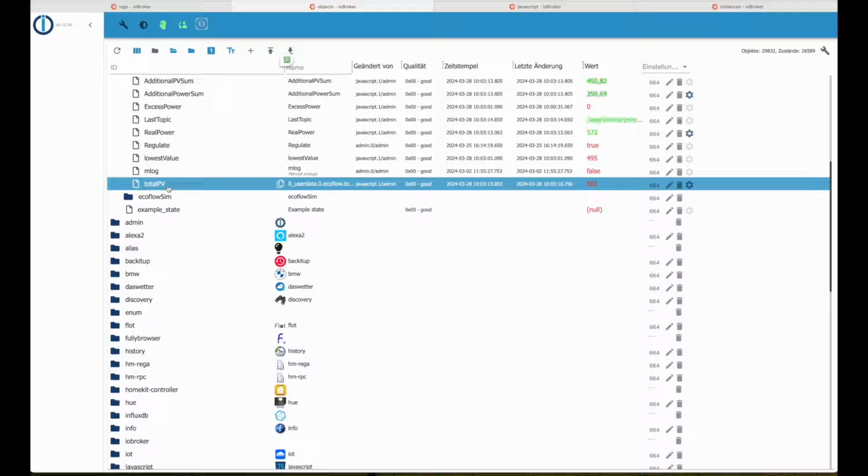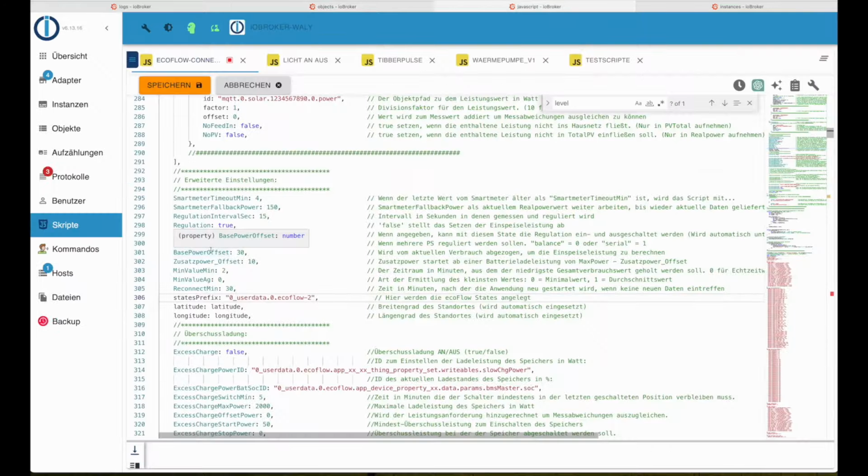If you go to your PowerStream there and look at the household power demand point in the settings, you should easily notice that the script dynamically adjusts this point in real time, providing accurate and timely updates. Of course, it's set to 600W if you're using more than 600W, otherwise it should just match the household consumption. Later in the smart meter, you can then verify and confirm if your script also successfully achieves this desired base power offset value. Once all of that is ready, then the script will start running for now, and then maybe you can start looking at the next configuration points.